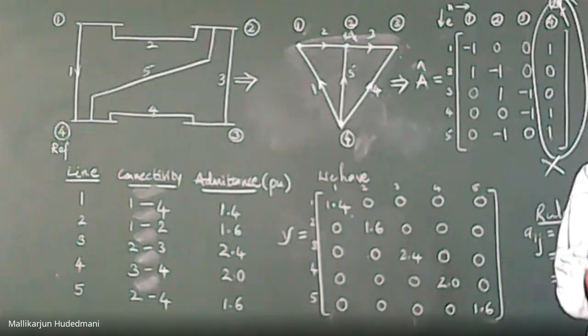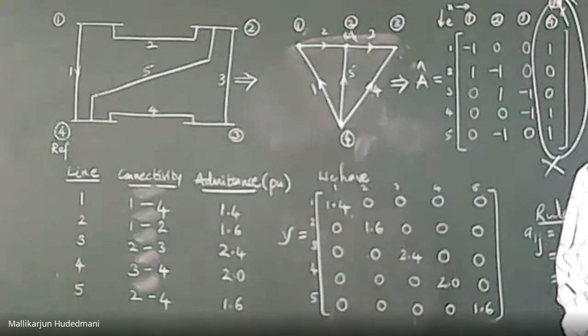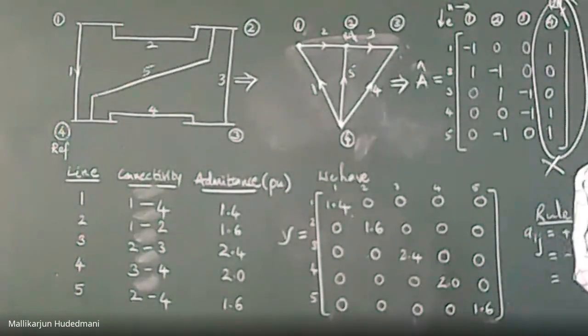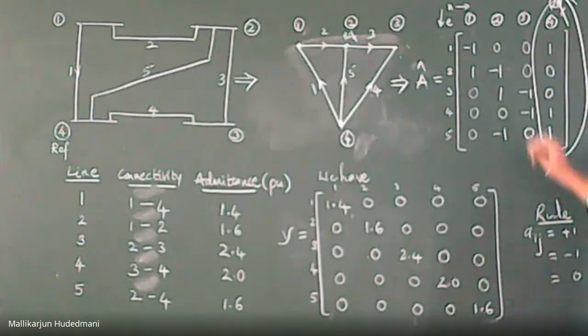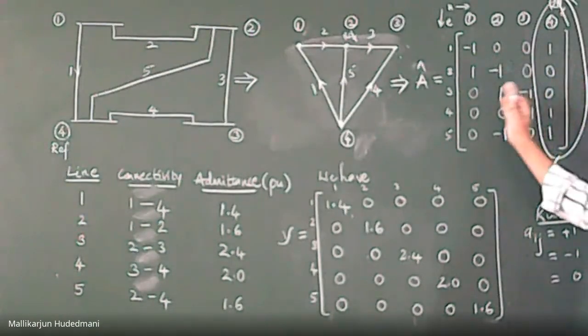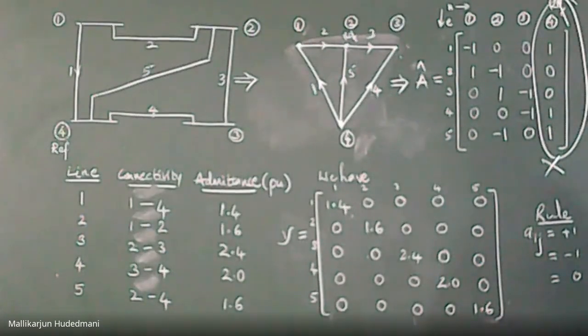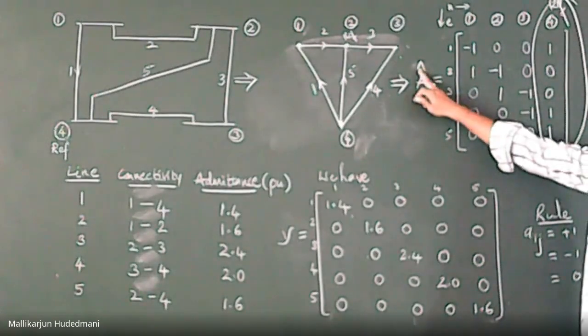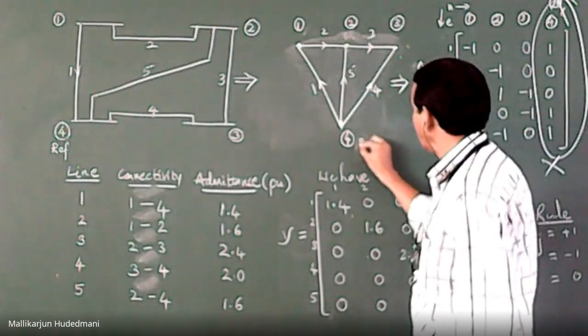At that time my sincere advice is to do the full house matrix, and delete whichever column you want. It is a matter of 30 to 40 seconds extra computational time, which ensures your work is perfect. So no matter whether it is the third or fourth bus reference, doing the full house and deleting is the best and advised way. Therefore, when I did the reference bus deletion, I took it out as per the problem given.